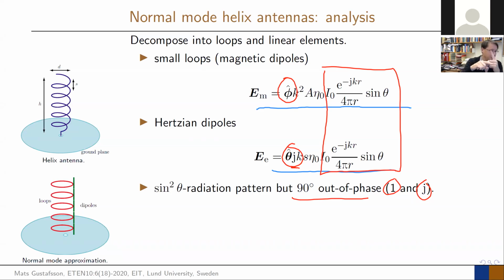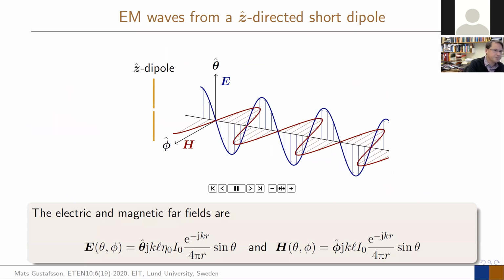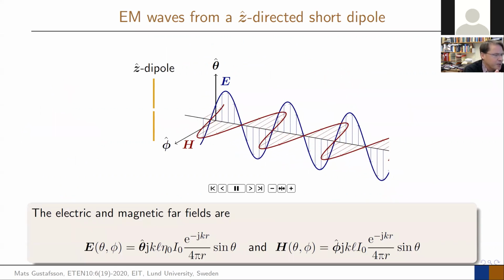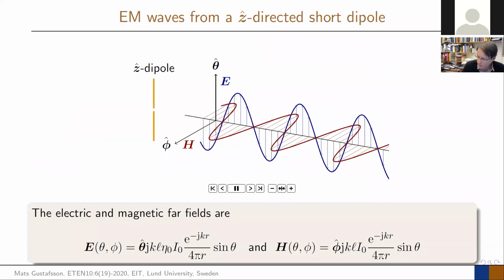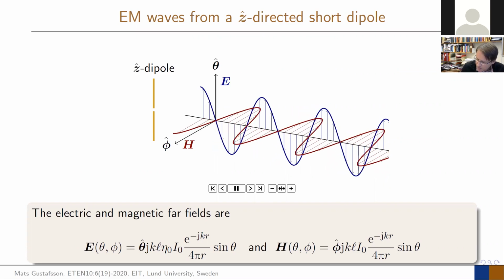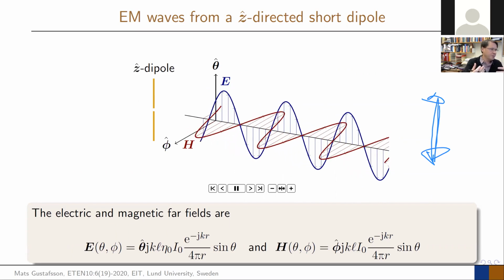And that is what will happen with this if not one dominates completely. If we take these antennas, the electric dipole part dominates so much that it almost behaves like a regular type of dipole antenna. But if you go for a slightly different one, they can get more balanced. So then look at the radiated field. If I take first my Z-directed dipole, I will have my current in these cases, the electric field just going in this direction, up and down here. So basically the same direction as the dipole.